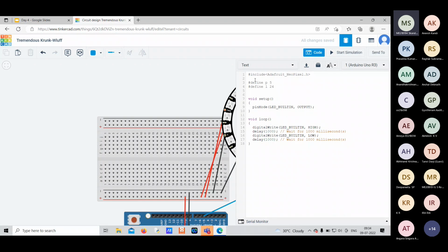Now, before going to the void setup, which is again beginning the NeoPixel, and the looping statements, which would repeat one after the other according to our desire when we click on something, before going there, we need to define something called an object. Which is again characteristic of libraries. So Adafruit_NeoPixel. Let me call the NeoPixel ring by the name H. So let's say even strip, that works.